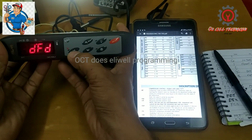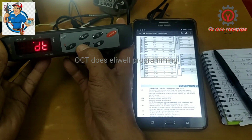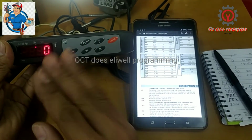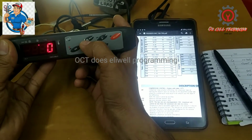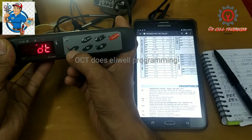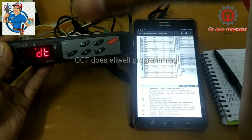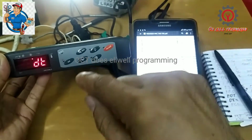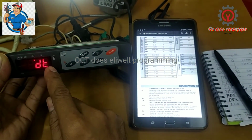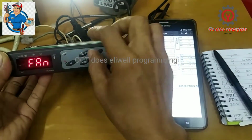If you want to put a value of DT, here's the DT, dripping time. So we delay it and we put a value of 1 minute, then set, and this one allows the water drip from the evaporator to go directly to the drain pan.